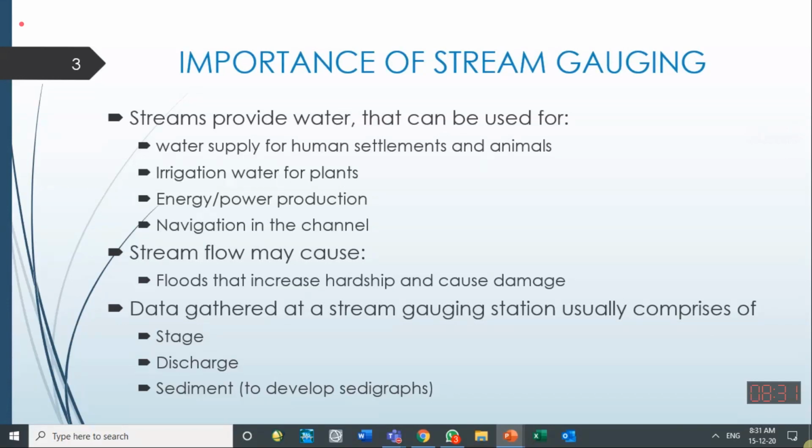I give you an example: a high flood in the Indus River at Chashma starts from 5 lakh, 6 lakh cusecs. 10 lakh cusecs is an exceptionally high flood there on the Indus at Chashma. But for the Ravi, maybe a flood starts from 100,000 cusecs.